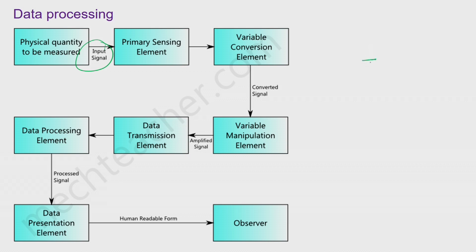So let us say your body is at some temperature T0 and the thermometric fluid is initially at some temperature Ti, and assuming T0 is greater than Ti, we are going to get a certain amount of heat transferred from the body to the thermometric fluid, which should be proportional to this temperature difference. That means some amount of heat will be transferred which will be proportional to this temperature difference, and this heat transfer will continue till the temperature of the thermometric fluid increases to attain thermodynamic equilibrium.